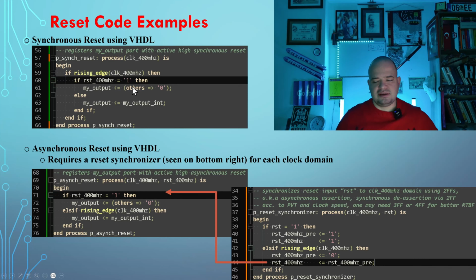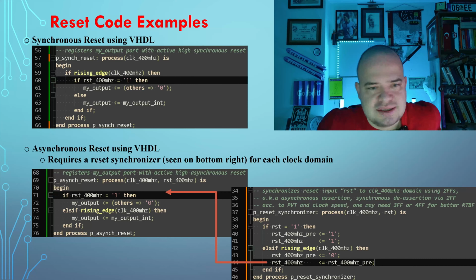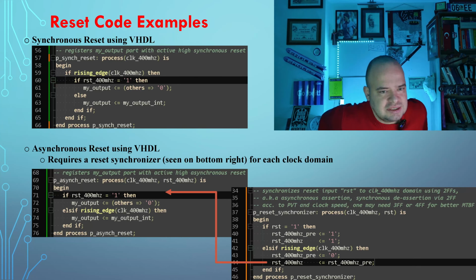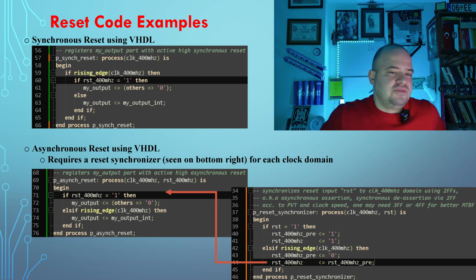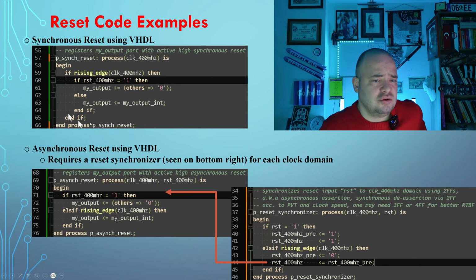Reset only signals that are in your control logic, that are important for your FPGA output pins or internal software dependencies. If you add each and every signal you declared in this entity of this process, then you are wasting different resources, like global routing resources.